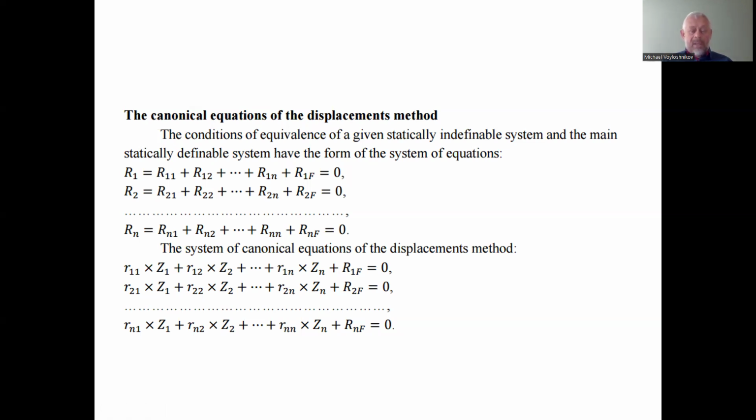And it could be extra connections limiting the linear displacement. In all directions of these installed extra connections, theoretically, we assumed as a part of the concept of canonical equations of the displacement method, the total of all forces acting, considering as well the forces under action of the external force, has to be equal to 0.